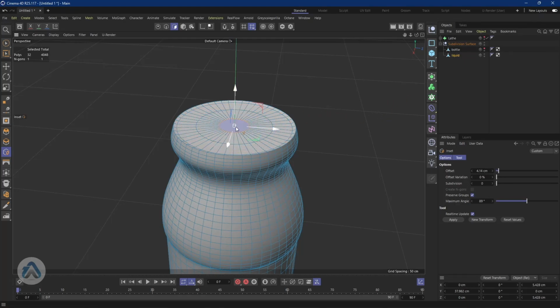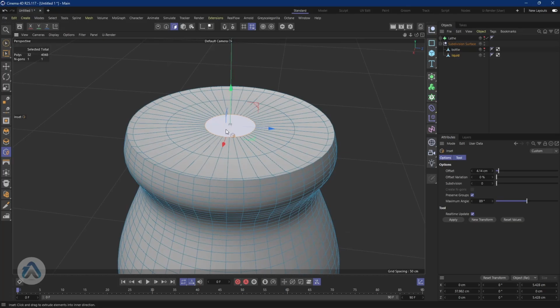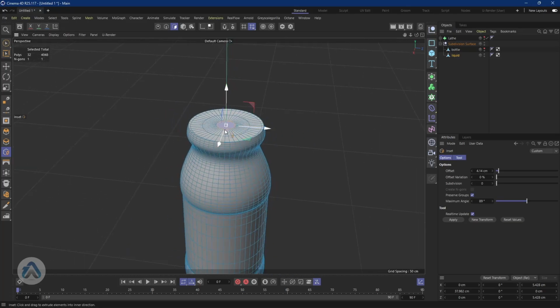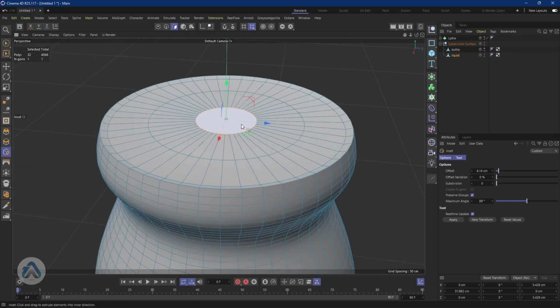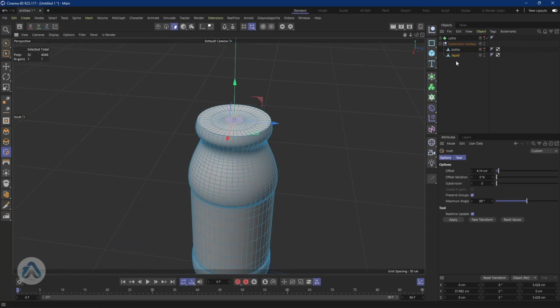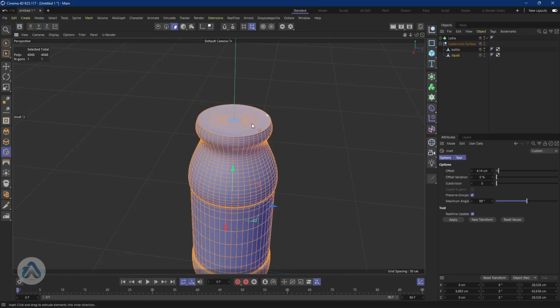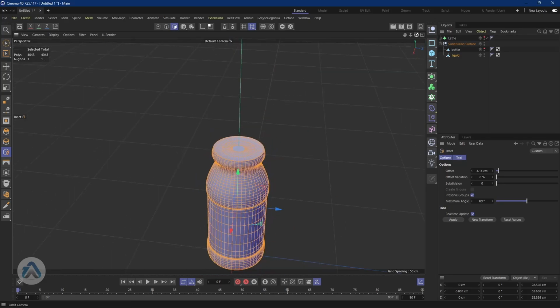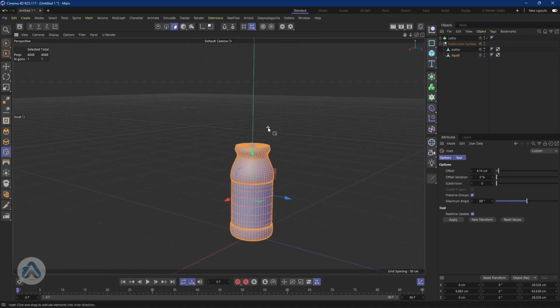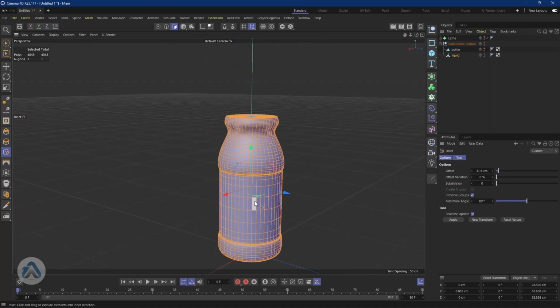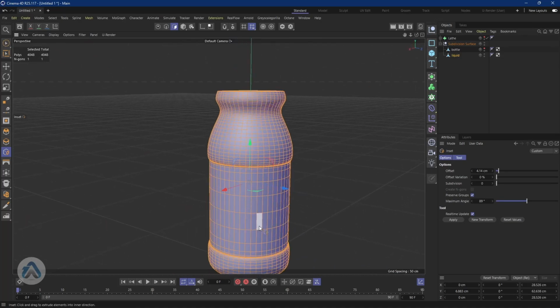It's okay. You can go on and create the parts, but for this the camera will not be in close range, and we are not going to UV unwrap this liquid, so we can leave it like this. When you select all the faces, you see that the color is blue. This means that the normals of this object have been reversed. We need to reverse the normals back.